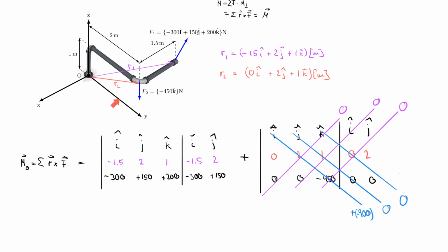So this force really rotates only about the x-axis, because this force in the z direction times its distance in the y direction, zy, gives you an x component. And there's really nothing else that you can cross this with, so that you only find a moment about the x-axis. And like I said, this is very simple.